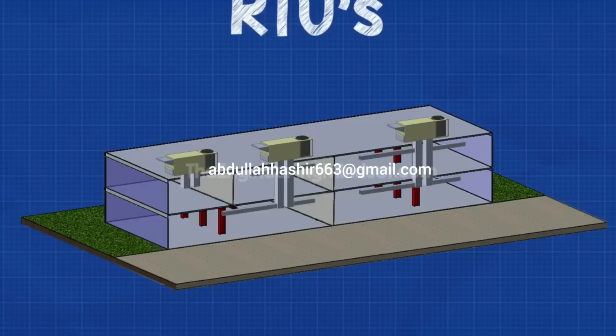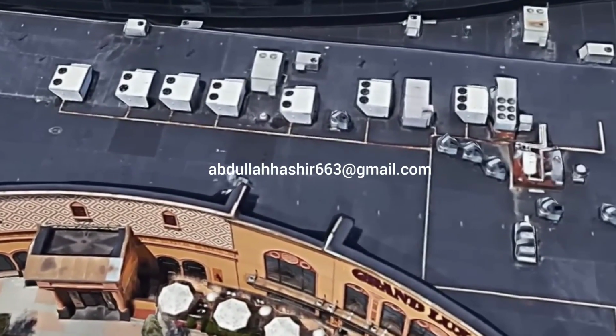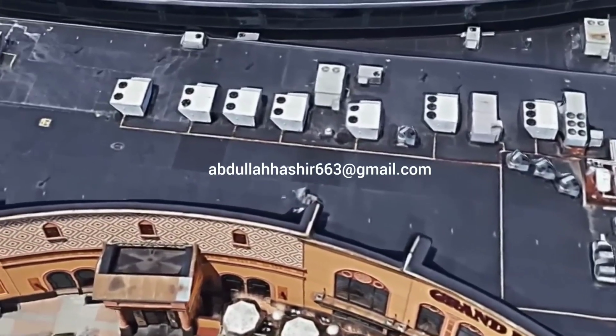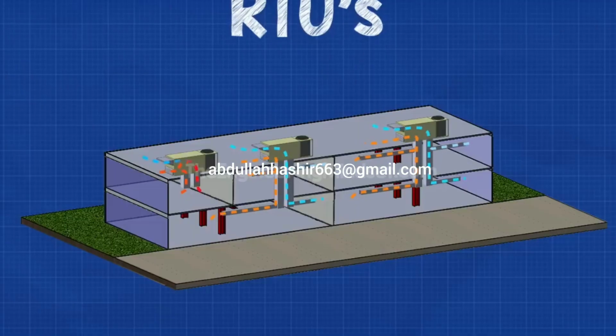RTUs, rooftop units. These units are always located on the roof, as the name suggests. They are very common in shops and small commercial properties and are popular because they are simple, compact, self-contained, all-in-one HVAC units. Their purpose is to distribute conditioned air around defined areas within a building. RTUs are also connected to ductwork, which provides a defined route for the conditioned air to travel along.